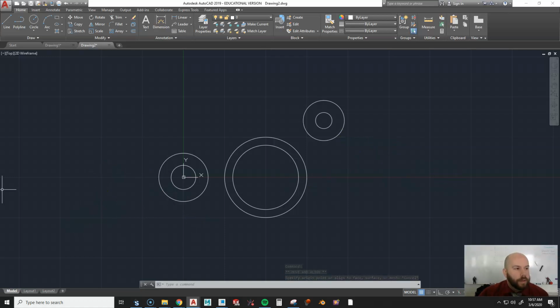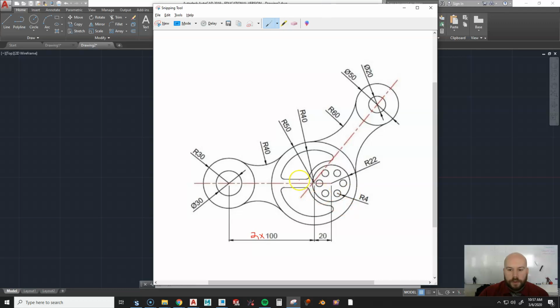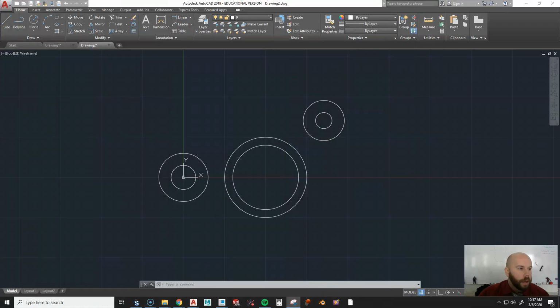All right, so now the next thing I'm going to do, I'm not going to worry about all this funky stuff that's happening inside here. I'm going to put in these tangent radii in here because I know the dimensions of these. This one's 60. I'm going to assume this one's 60 as well. I don't know why it wouldn't be. But again, why not just have a 2 times in front of here? It takes 2 seconds in MS Paint to do that.